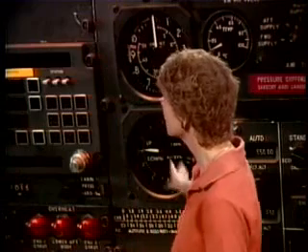Now let's assume that you're climbing to altitude, but the cabin rate of climb is too great. You're looking at the cabin rate of climb indicator in the pressurization system, and the cabin is climbing too fast. What does the FAA say you want to do about that? The pressurization control should be adjusted in that case to cause the outflow valve to close faster.